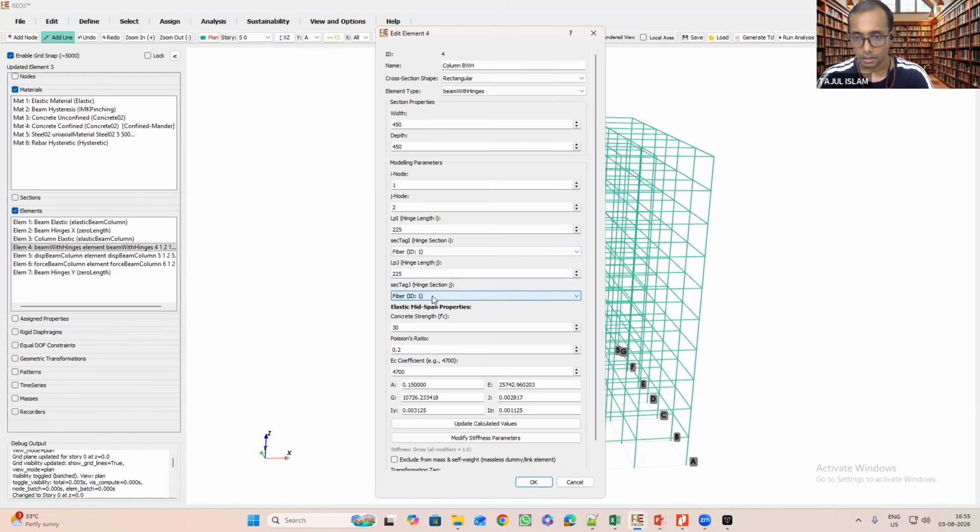And again this is the fiber section for the other end. Then here you define the grade of concrete, and this is the coefficient for the Young modulus of concrete. As per Indian code, it is 5,000 root fck. If you are out of India, you might be following some other codes, and according to that you can define here. Update.